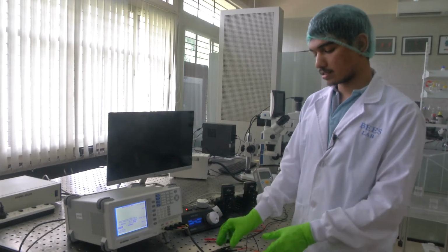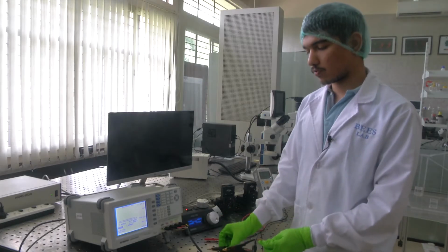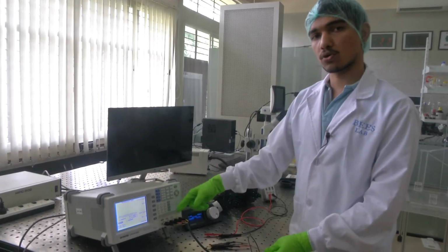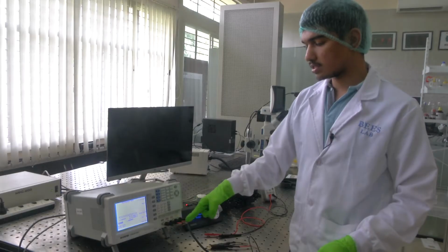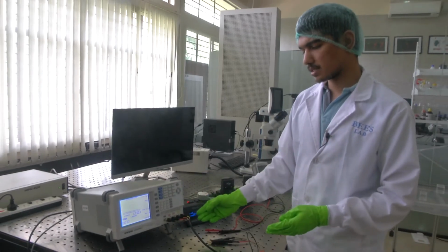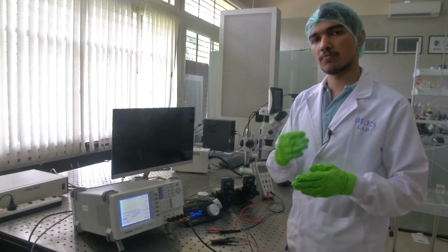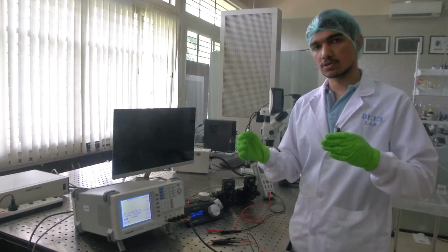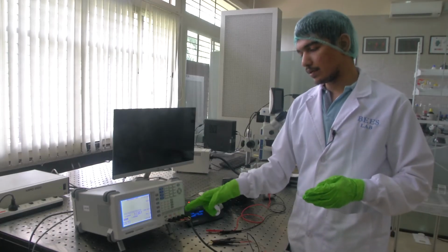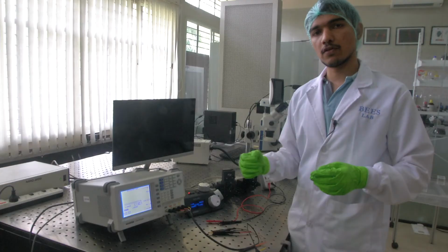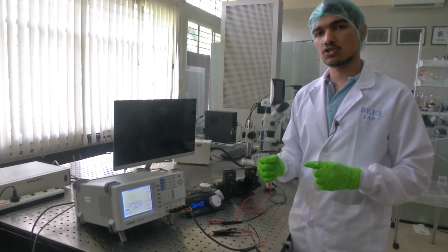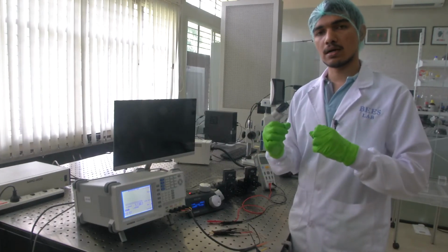In the case of a 4 probe, the current or the potential is applied across the forcing probes. The voltage drop happens across those, and using the separate sense probes, we measure the actual potential drop across the DUT.